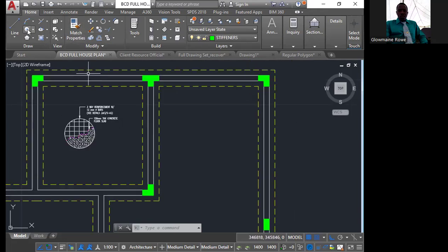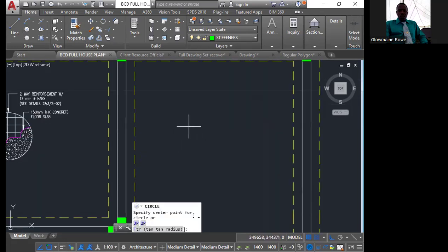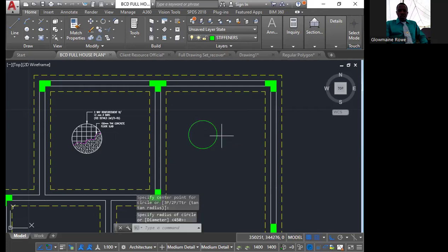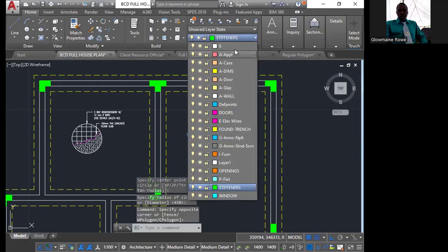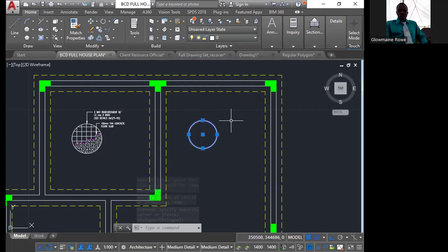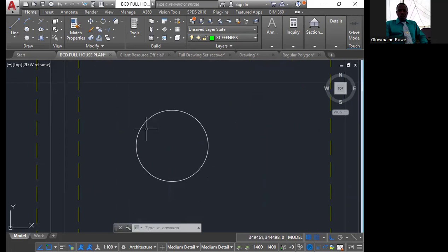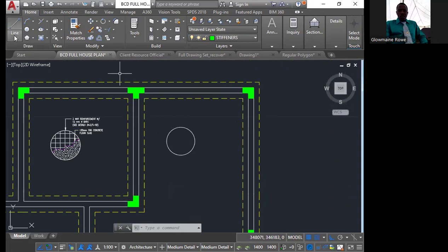you're going to select the circle command, make one in the kitchen here. Click. This circle has no specific size, it's just a symbol. Mine is on the zero layer. Everybody has this circle. All right, somebody asking about the size? No specific size, it's a symbol.